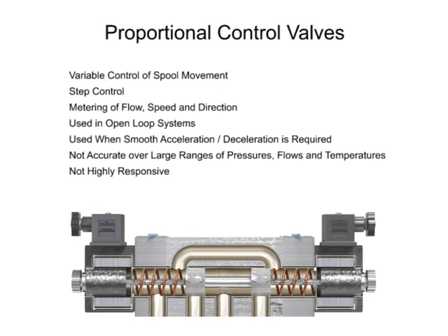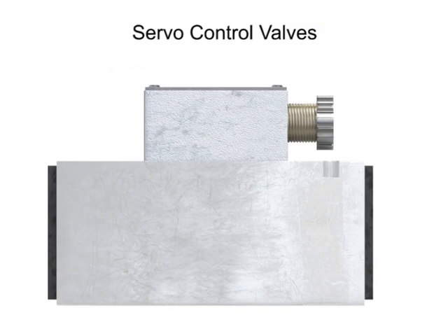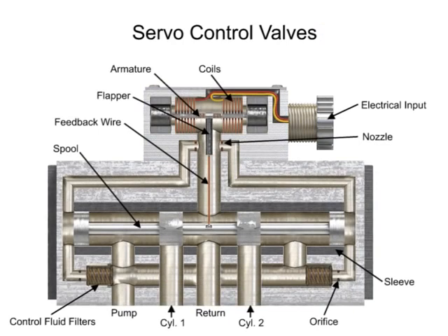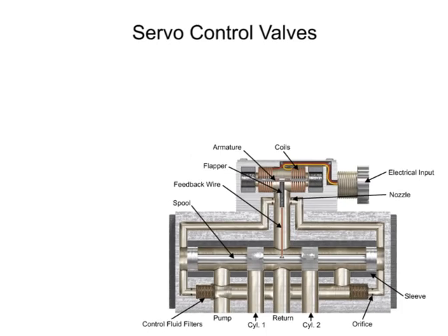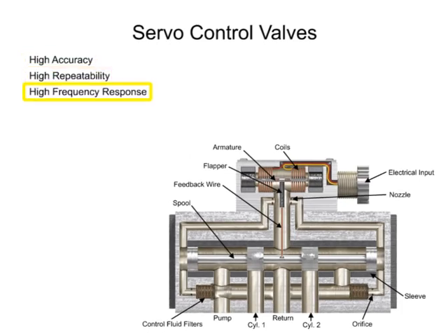Proportional valves offer a variety of machine cycles which can safely be operated at greater speeds and result in improved machine cycle times and production rates. The third type of hydraulic directional control technology is called the servo valve. First developed in the 1940s, the servo valves operate with very high accuracy, repeatability, and high-frequency response.